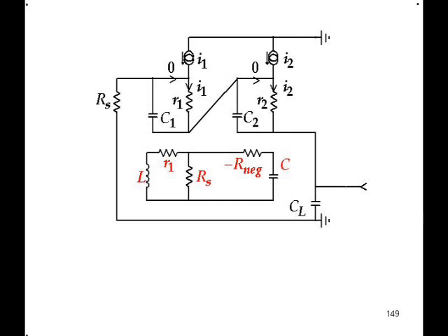Well, it may or may not oscillate depending on which of the damping resistances is dominant. Basically, you have two series damping resistances and one shunt resistance. And one of the three is negative. So it depends whether you get an instability or not. Now that's the physical interpretation. What can we do about designing it so we make sure it doesn't go unstable? But more than that, we don't want any excessive peaking in the transfer function.